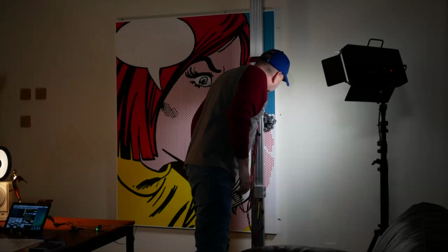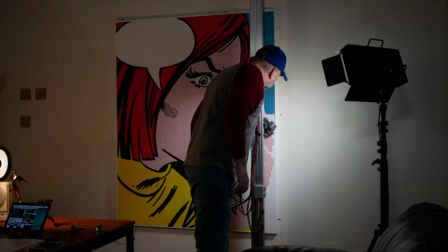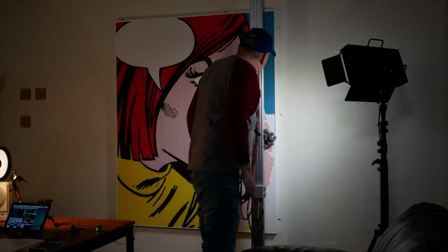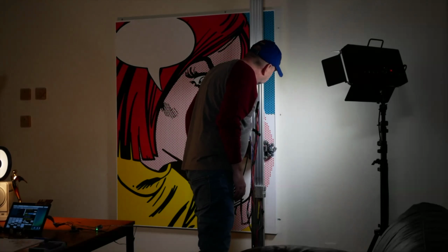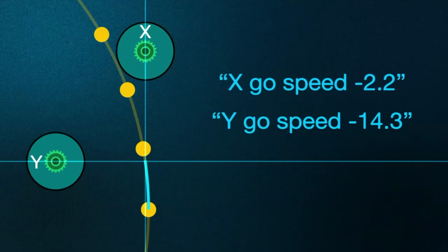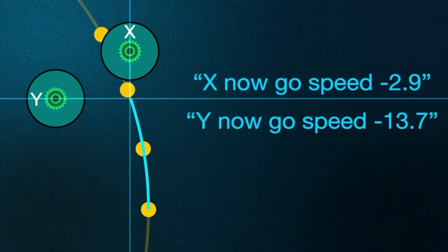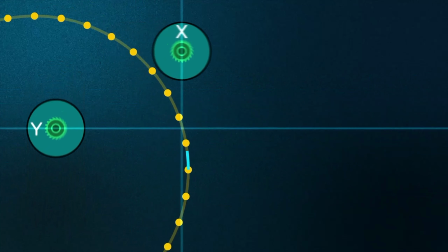Another complexity is that I don't want multi-threading or other activities taking up computer time while it's drawing. If the pen is down, I need 100% control of the Pi. So each loop is a hard, tight loop because timing has to be perfect. I'm telling the motors to move at a particular speed. Then a few milliseconds later, I tell the motors to move at a new speed.